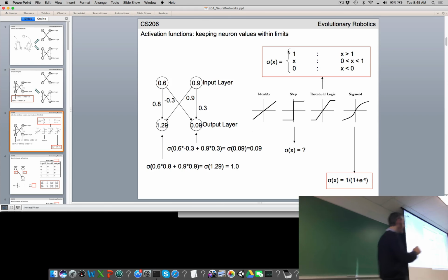The reason why we're using the tanh function and we want to squash things between -1 and +1 is that you're going to start to send the values of some of the neurons to the motors, right? And we're going to output to the motors a desired angle for our joint. And in the robot that you're working with right now, we're going to assume that a joint can rotate between +45 degrees and -45 degrees. So we have a range of motion for that joint. So we're going to take the value from the motor neuron, which because of the activation function we know ranges between -1 and +1. And we're going to scale that to lie within the range of -45 to +45. And then we can send that as the desired angle to the joint.